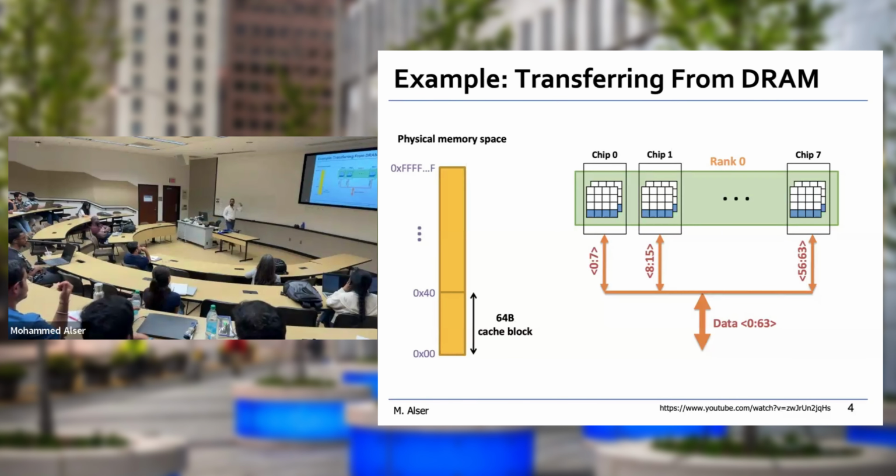So whenever we have a clock cycle, all of them are still sharing the address, the control, which is the command to read or write, or to activate a row and so on, plus the data itself. So when those chips return data, all of them share the exact same bus. That's why you can see over here the bus, which is 64 bits, shared among all these chips.